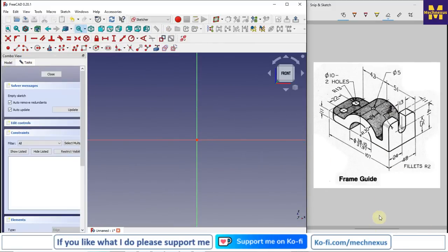Now we will study our model. So first we will make this profile, and then we will do extrusion of 48, and then we will adapt the rest of the features. So let's start. So here we will keep our center at our origin.